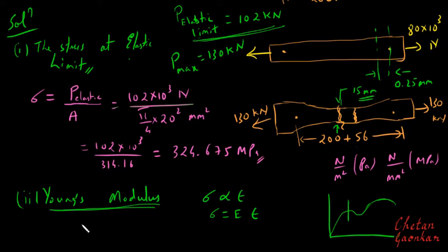So therefore we will be able to find this Young's modulus E as sigma divided by epsilon. All these quantities, stress or strain, used to calculate Young's modulus should be within the elastic limit. We cannot consider any values of stress or strain beyond this point to calculate the Young's modulus. Whatever stress or strain quantities we take to find Young's modulus should be within this elastic limit.